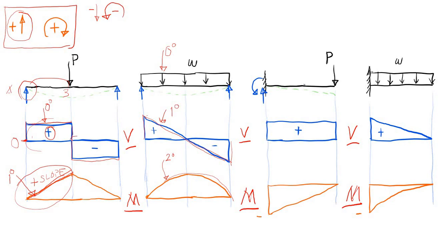Now, from this point to this point, since our shear diagram is now negative, then we will now have negative slope, because this area now is negative, below our 0. And again, since this is 0 degree, then this must be first degree. Another, for our uniformly distributed load, 0 degree our loading, first degree for our shear, and second degree for our moment.